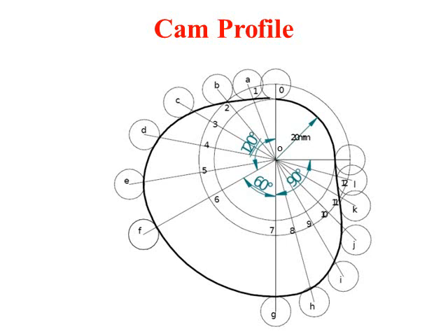Next step is we have to transfer the values from the displacement diagram to the cam profile. So to transfer it, go back to the displacement diagram, measure 1A, and with 1 as the center, that is 1 lying on the prime circle, cut an arc.